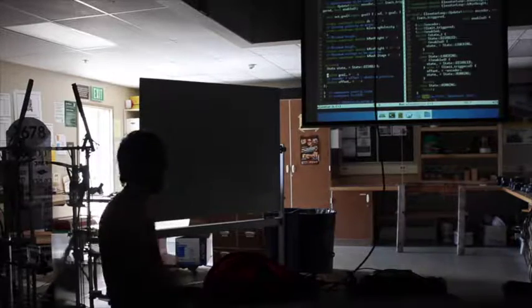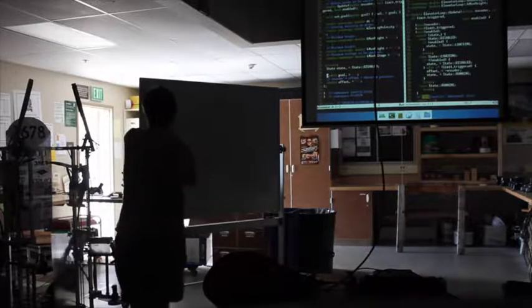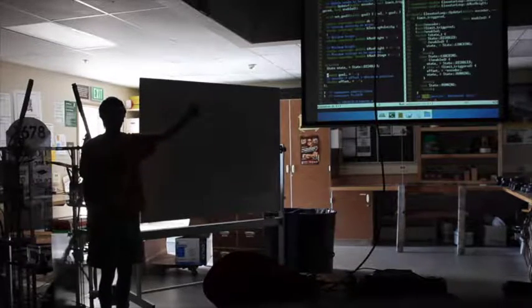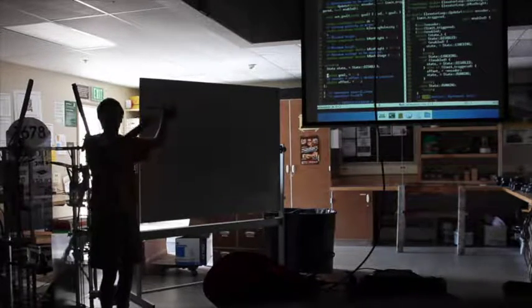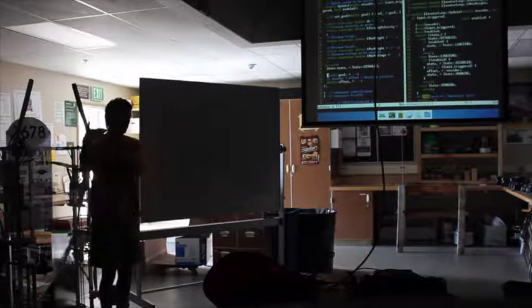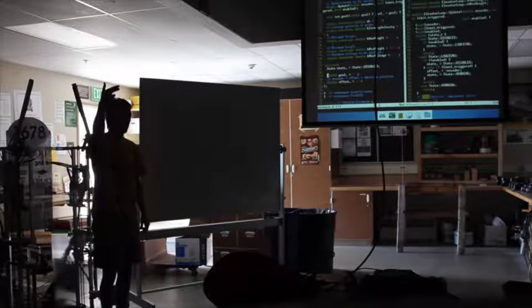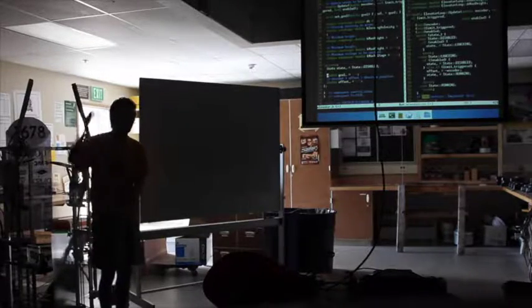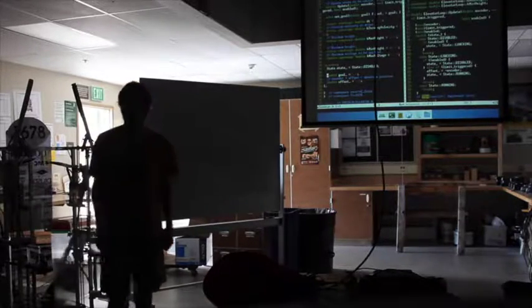This is where the disabled state comes in. So when we're disabled, we want to reset it to tell it to go where you started. And then every cycle, we want to move it down a little bit, move our goal down. And then when we feed that to our control loop, it will slowly execute this path we've given it. So it'll start at the top and then slowly move down in a very controlled manner until we get to the limit sensor, and then it will jump to wherever we asked it.